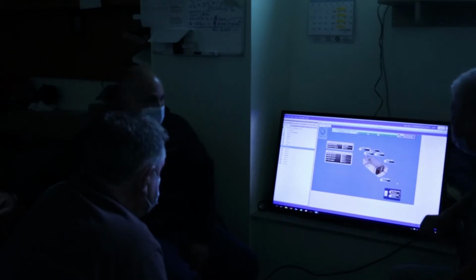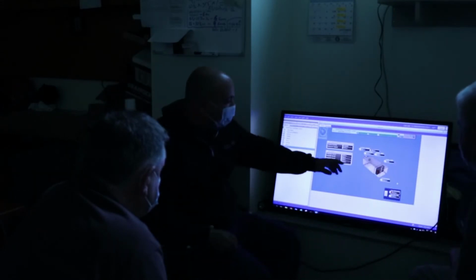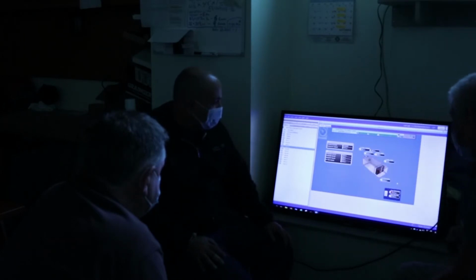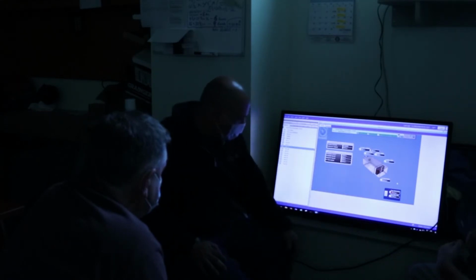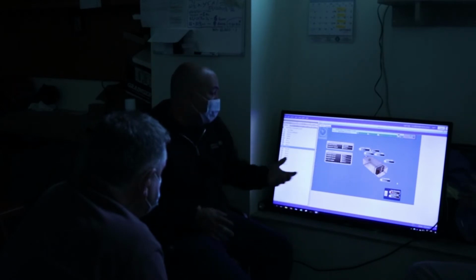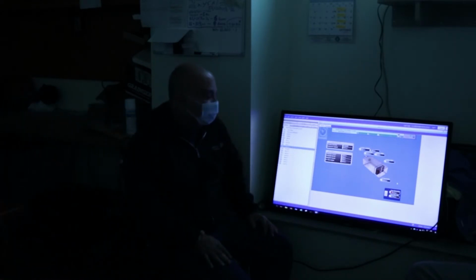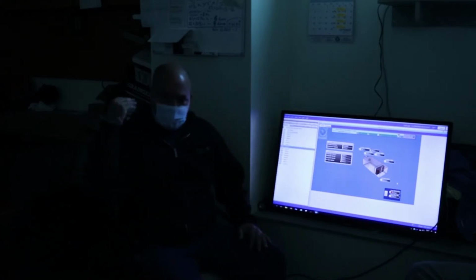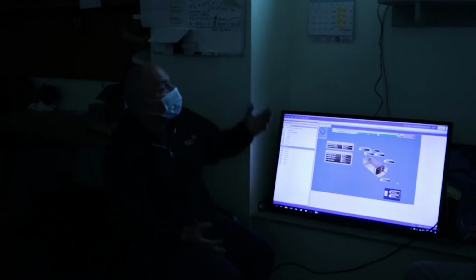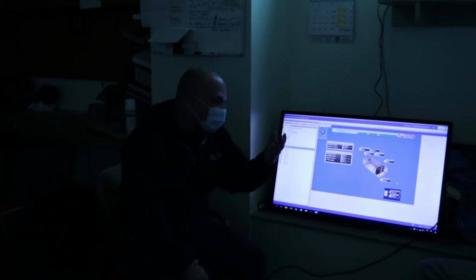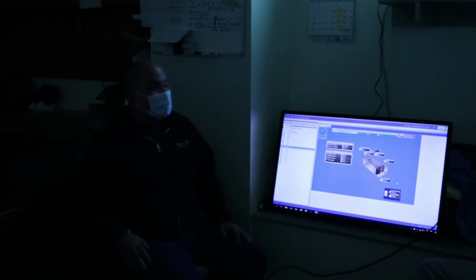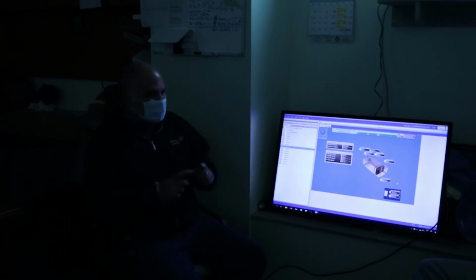The damper should be open 100% now. No, so the damper will... I understand it's maximum it's 200, but in this condition, it should be open more. Well, we don't know what's causing this condition. Could there be a coffee pot in front of the sensor? Could the shades be up and maybe there's a direct sun load on it? I'm just throwing out examples because I have seen a sun load, especially with these thermostats. Let's call them sensors because they're not really thermostats. These sensors are stainless steel, so if they do get a direct sun load on them, they do heat up.